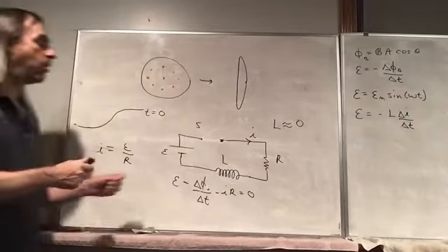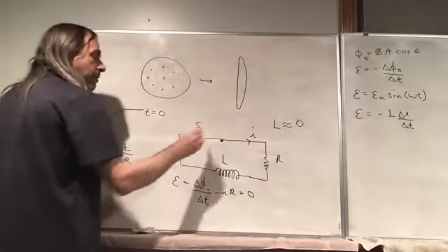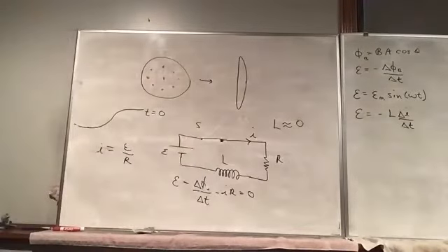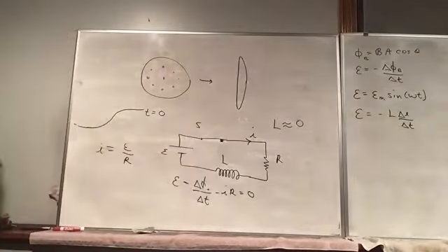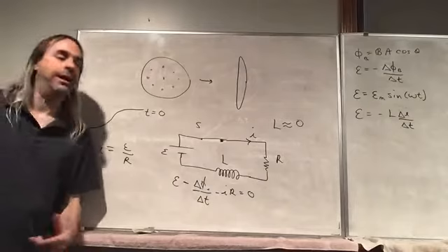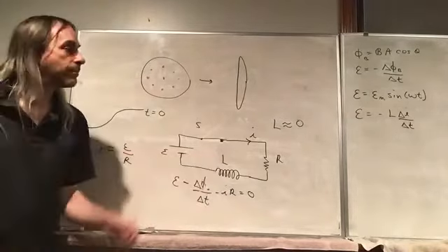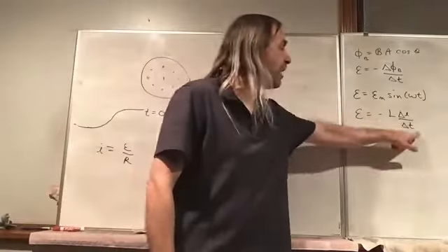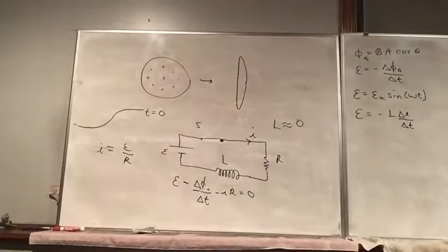And again, this is still what we call a direct current, because we just have a battery providing a constant voltage. Things can get very interesting if you were to plug something like this into an outlet, because there the current's constantly changing. Remember, inductance acts kind of like inertia. It resists changes in current. So if you try to rapidly change the current, you'll get a very large back EMF to oppose that.